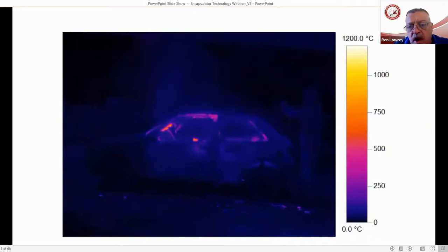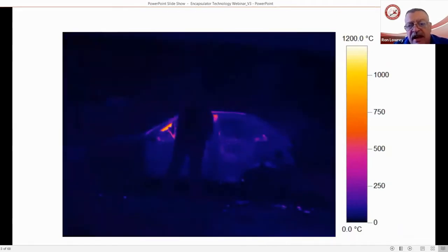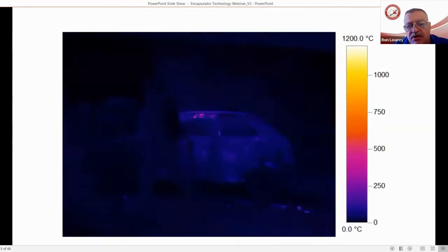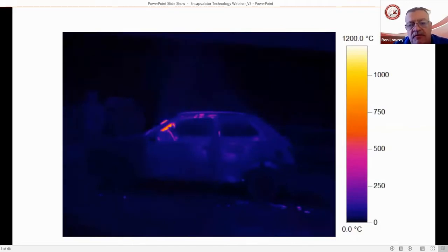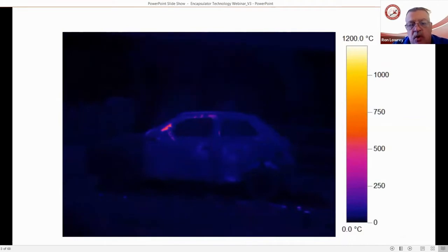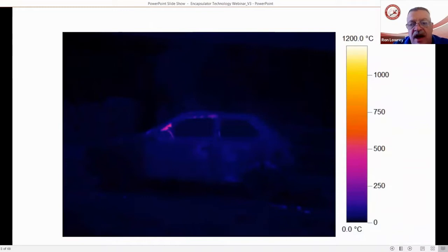Again, a 20-gallon per minute flow, so a very low flow. As you can see, he's not constantly flowing that nozzle. He's using it in bursts. So far he's maybe flowed 10 gallons of a 1% solution of F500 onto this fire. You can see the rapid drop in temperature, how quickly that heat is removed, how rapidly the fire goes out.